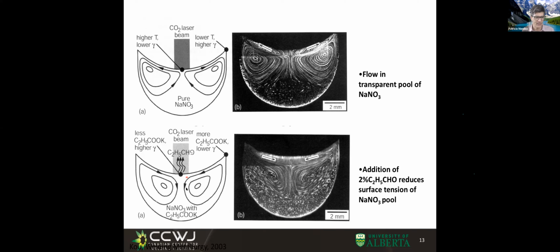And I don't know what the proper name of this weird component is, but with the surface active element, you can reverse the direction of the Marangoni flows and create a jet that goes down, right? And this takes everything that is hot on the surface of the weld pool and brings it into the penetration. This is the mechanism of penetration when you have recirculating flows.